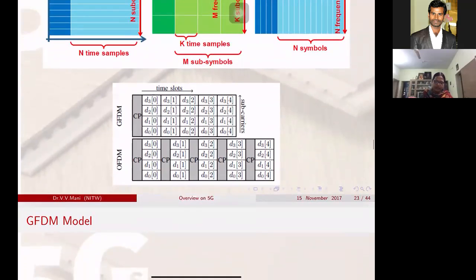So for these 4 data samples, I have added a cyclic prefix, right? Because if you remember your diagram, at the end of your IFFT block, there is an addition of a cyclic prefix. Then at the next time interval, again 4 data samples, a cyclic prefix. Like that, as the data stream comes in, I take serial to parallel conversion and I map accordingly. After mapping them, I port onto the N-point FFT.